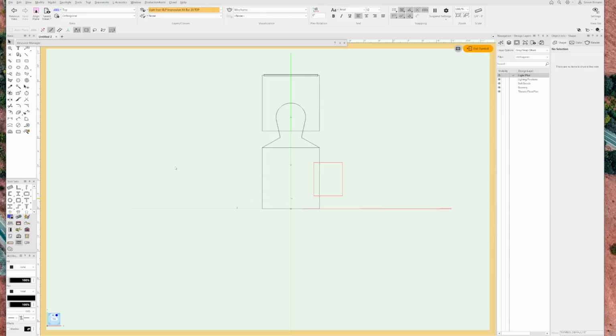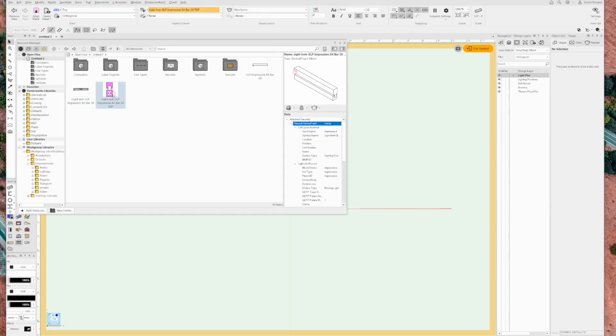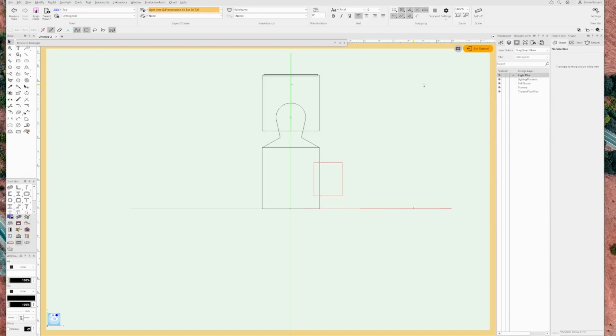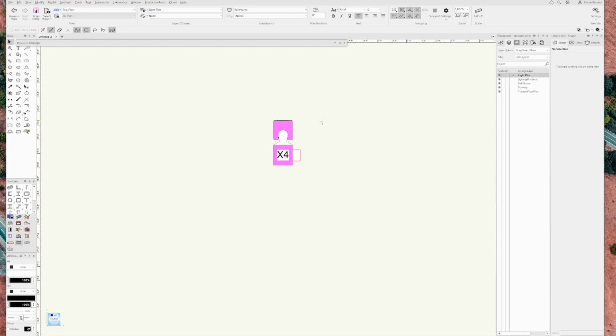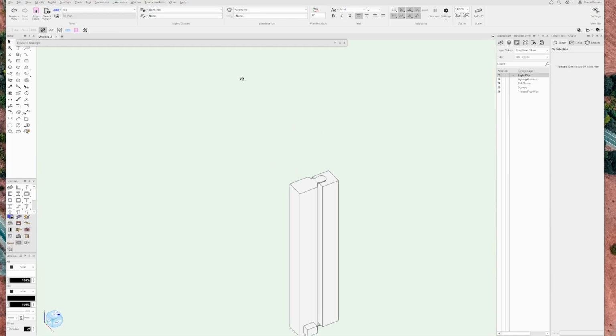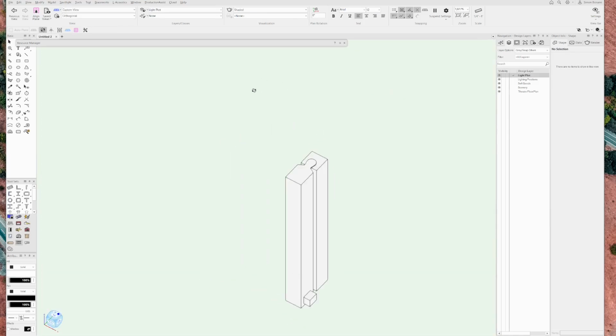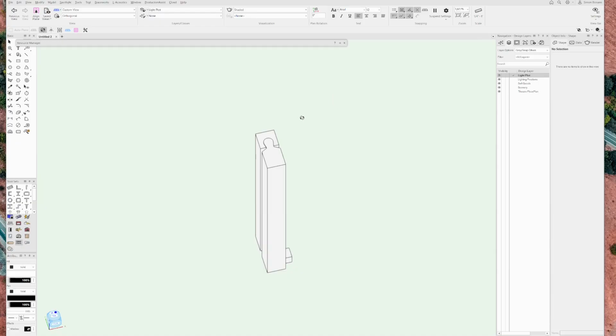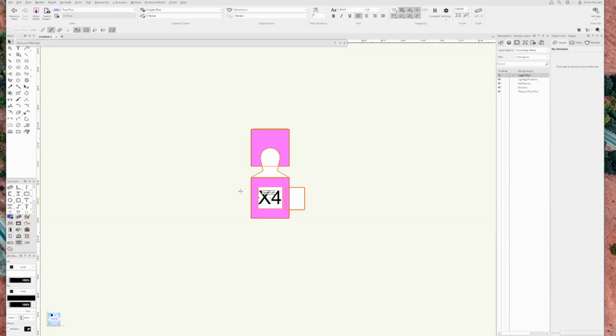So the base is on the bottom, fixture is on the top, and the connectors are on the right. And that was exactly what I drew here in the 2D as well. To make sure, exit this. And now if we look just simply at the 3D, it looks fine. It's installed vertically. And that's what the 2D outline of the 2D, 3D hybrid symbol represents.